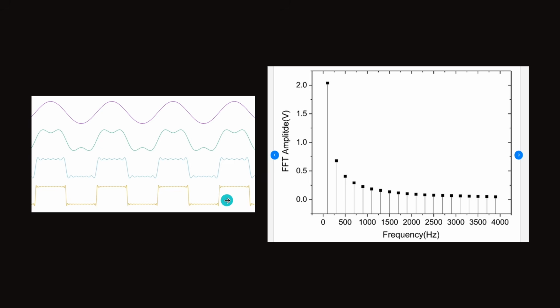One more thing to understand from the theory. When we have a pulse signal, and I said that at clipping we have a pulse signal, here is a spectrum of the pulse signal, or Fourier transformation of the pulse signal. Imagine you are clipping at 300 watts, and then you have a second harmonic, and third, and fifth, and many harmonics.